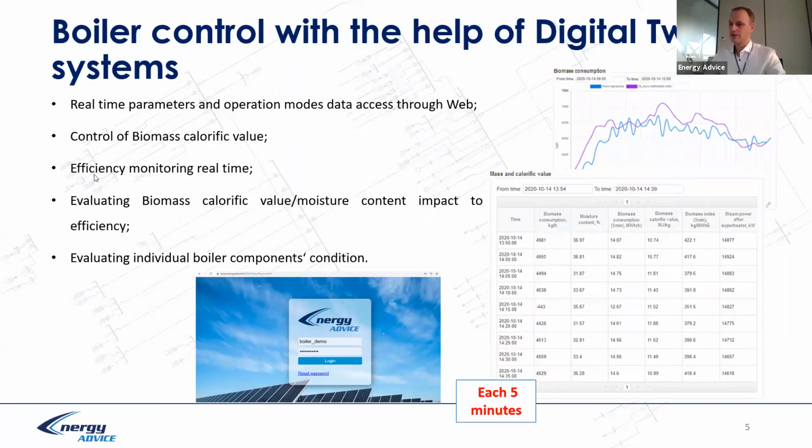You monitor efficiency in real time, and the calculation is done every 5 minutes. You evaluate biomass calorific value and moisture content, and also understand the impact on efficiency. And you evaluate individual boiler component conditions. It's very interesting, but you can evaluate and we calculate individual component conditions in real time every 5 minutes.